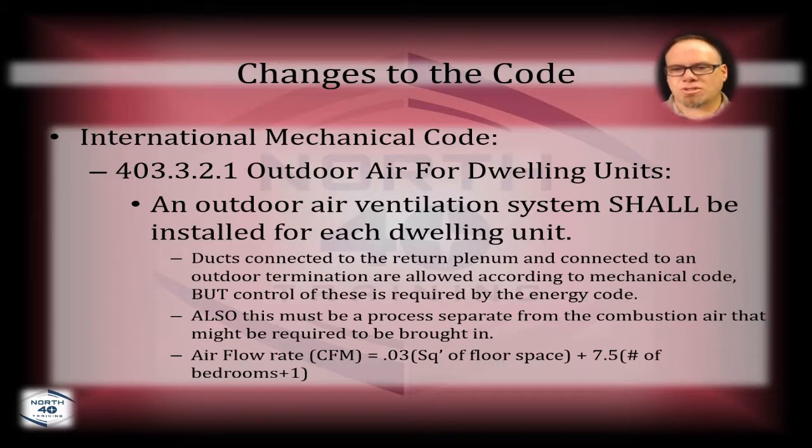Well, now we're also saying that you have to bring in air for people. And energy code says those have to be two separate processes. You can't use the combustion air coming in as a default for your air changes per hour for occupancy. You want to add a little bit more difficulty to that? How far can you be from an exhaust on an appliance to an intake that comes into the home for human occupancy?